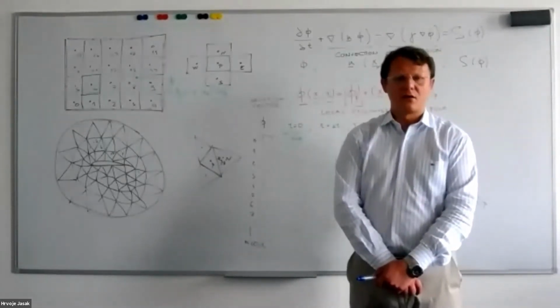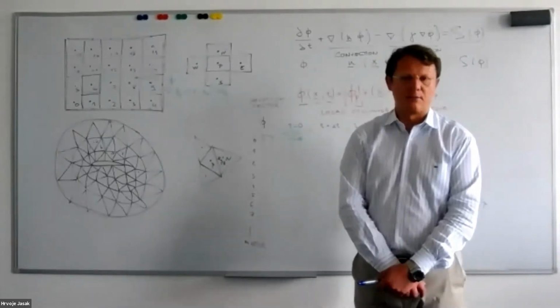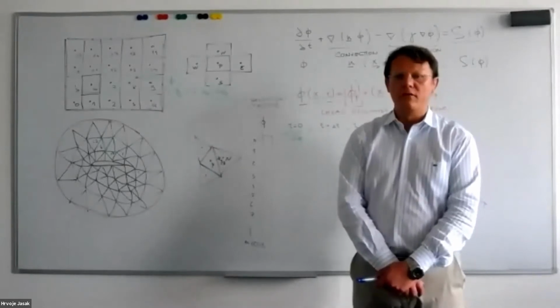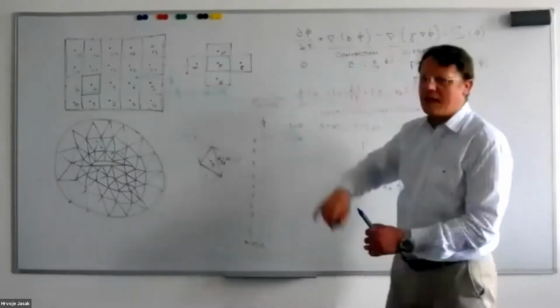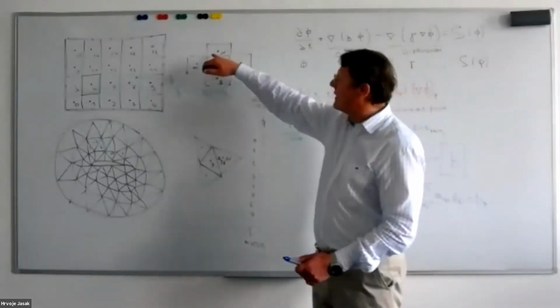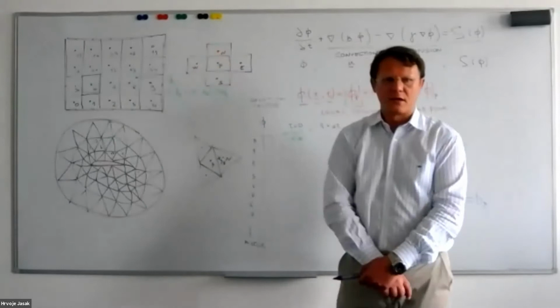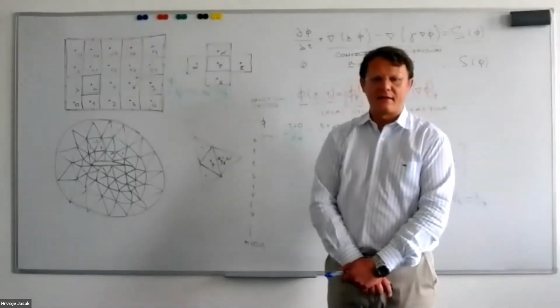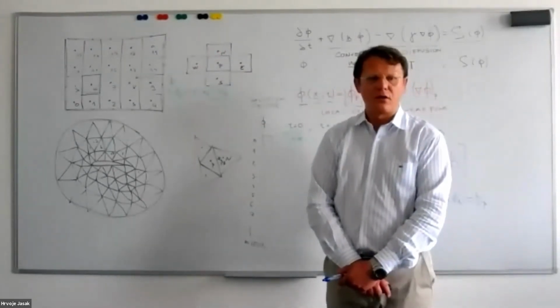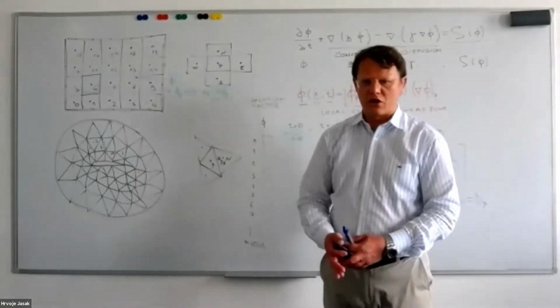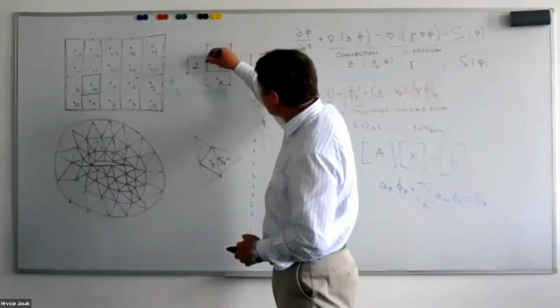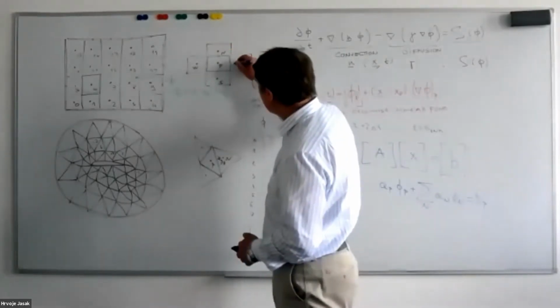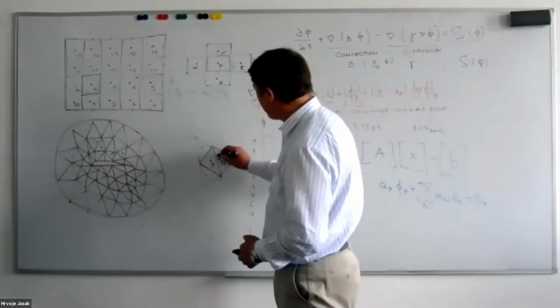So one of the tricks within the discretization that I will use regularly is called the Gauss theorem, which allows me to move the volume integral of the divergence operators into a surface integral over the outside surface of the cell. In order to handle that, I need to introduce auxiliary computational points, which are located in face centers, and I will refer to them as F.